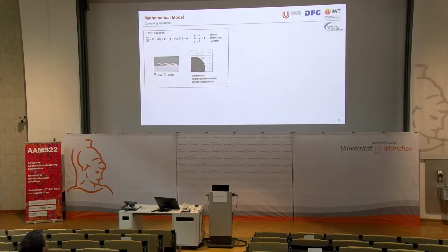The governing equations. We have 5 governing equations. The first governing equation is the VOF equation. If you look at the simulation domain, we have 2 phases: one is the gas phase and the other is the metal phase. The purpose of this equation is to capture each phase. With this equation, we can capture the gas phase, the metal phase, and the interface between them.